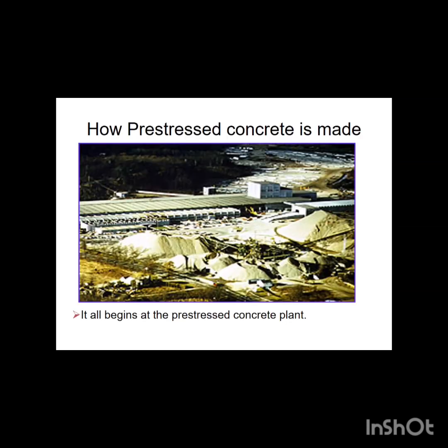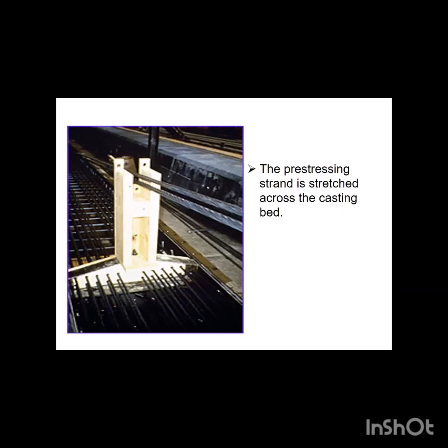When concrete has gained sufficient strength, the tendon is stressed, and the sleeve is filled with grout under pressure through tubes placed at intervals along the sleeve. The grout bonds the tendons to the sleeve, thus enabling the transfer of stress from the tendons to the concrete. How is pre-stressed concrete made?